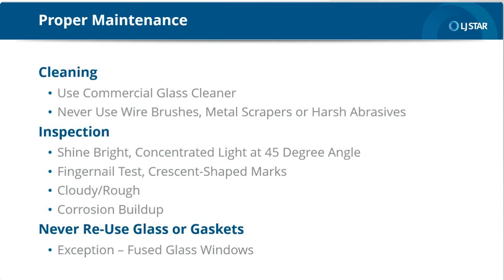Here's how to keep your sight glasses clean. Use commercial glass cleaners. Never use wire brushes, metal scrapers, or harsh abrasives. Do not attempt to clean the glass while equipment is in operation.